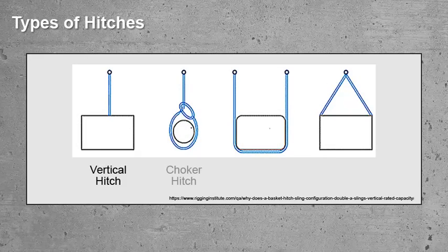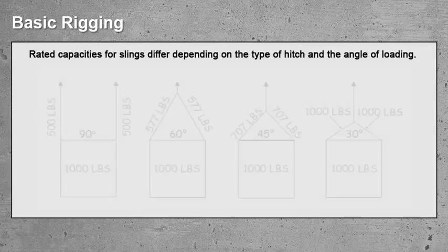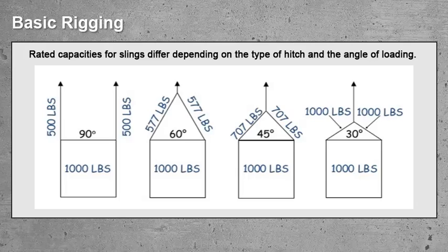These are the types of hitches used when lifting loads. Different hitch types are used based on the sling, the load shape, size, and weight. Also, the weight capacities vary depending on the type of hitch used. During this course, we will review rated load capacities for each sling. However, there are many factors that determine those capacities. This presentation will review the characteristics of the slings that determine rated capacities, but it is important to note that rigging practices also play a huge role in determining those capacities.